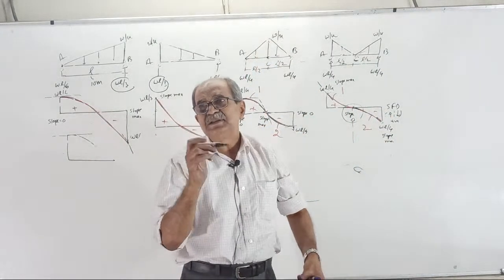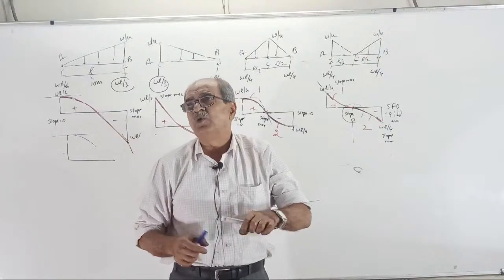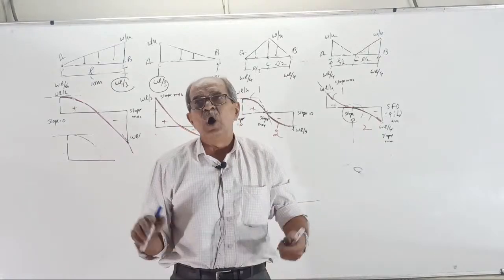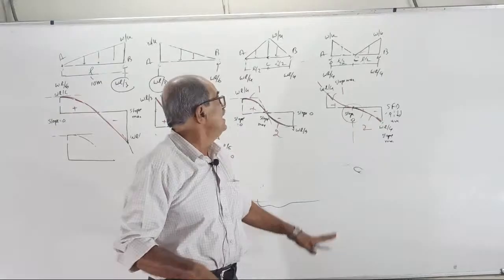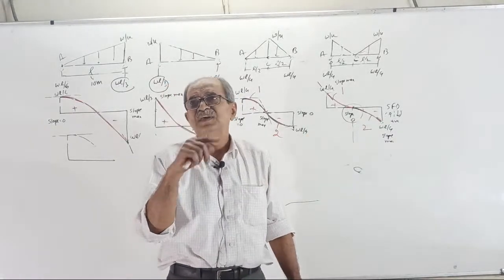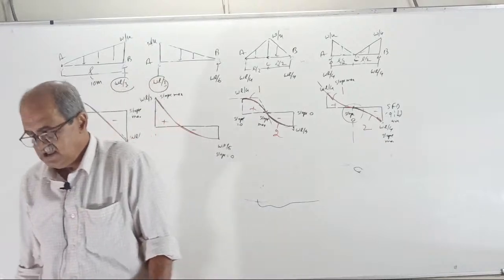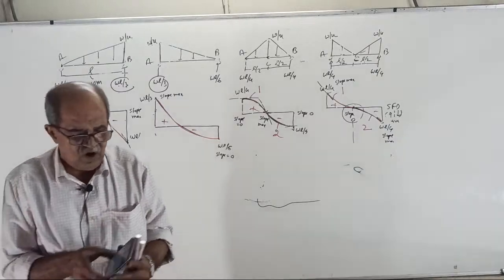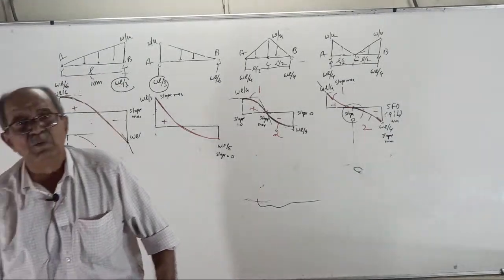This is the correct principle of drawing the shear force diagram, or how you decide the curve for the shear force diagram. If UDL is there, no curvature, shear force is linear. Be happy. If UVL is there, follow this principle to decide the type of curve. Fully clear or not? Tell me. Fast I want. Yes. Now, I will tell one more thing for you.